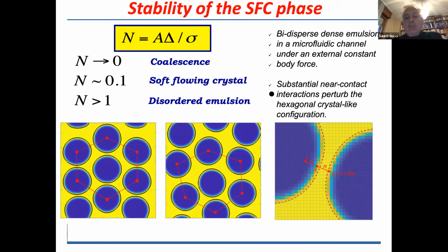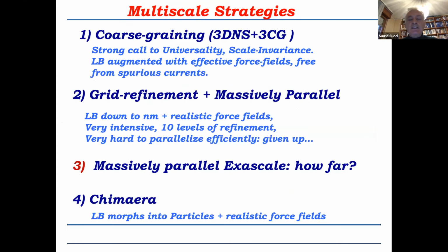And then your error is in the order of the percent or even less, okay? So that's the bottom line. Of course, those would be very long stories, many papers, etc. But the reason why I'm emphasizing this fact that the Cahn number can be tricked is because, and we didn't know that beforehand, it allows us to use much larger delta x.